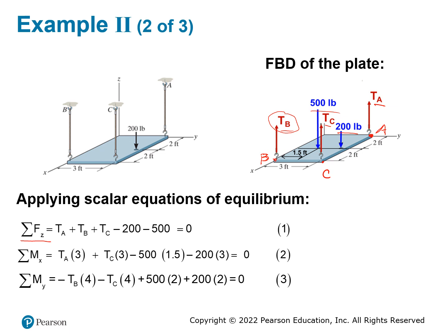So you just need to consider the rest of the 4 forces to find the moment around this point. This is a static problem, meaning there's no rotation, meaning the summation of moments at that point will be equal to 0.